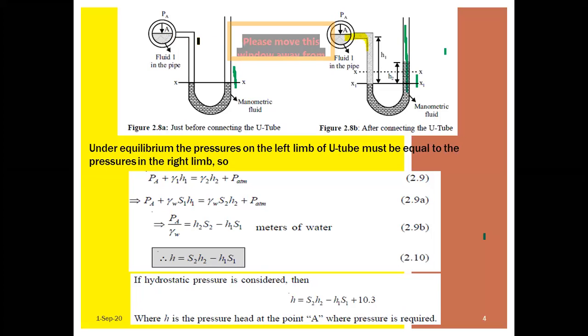Now the pipeline carrying the water has the connection of mercury. If you see the U-tube manometer, the manometer is having mercury as a fluid. Now the pipe carrying the water has a connection of mercury manometer connected to the container. The readings are measured as shown in the figure. Find the pressure of the water flowing in the pipeline.